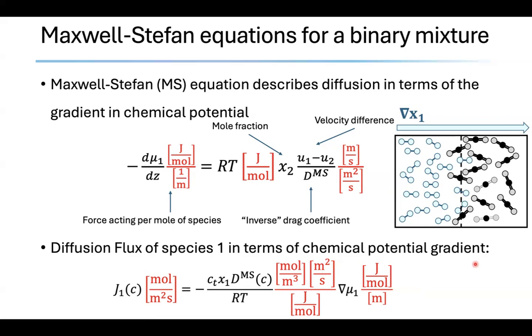It is well known that for phase equilibrium, the chemical potential of component 1 in either of the phases should be exactly equal. Thus, it is intuitive then that a gradient in the chemical potential will affect mass transfer. So, in other words, you can think of the gradient in chemical potential as a driving force.